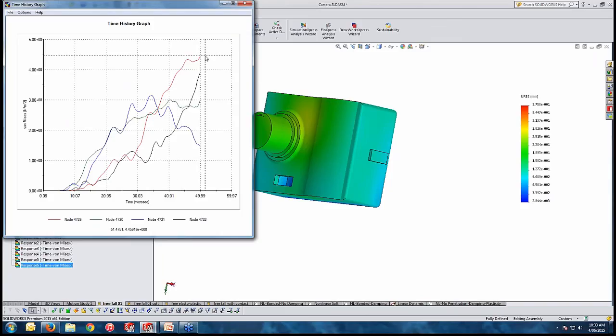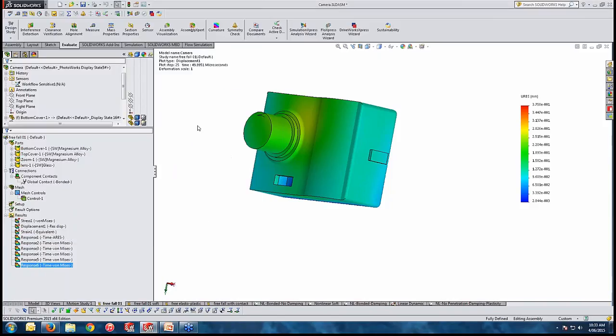So you can see quite high stress values on the first node, and the others are much less after the impact happens. Now, we are not going to analyze the result this time, but what we are going to do is make these cases closer to reality by considering, let's say, a flexible floor or making an assembly with contact between the components and looking at the stress values there. All right, so this is the basis of drop test, how we set up and how we record the results.